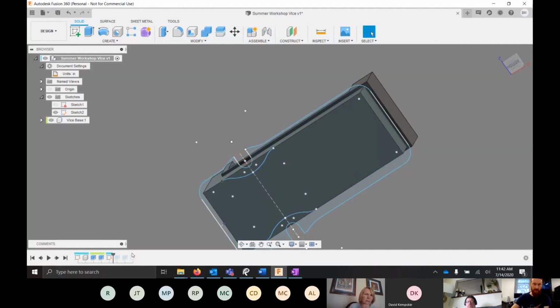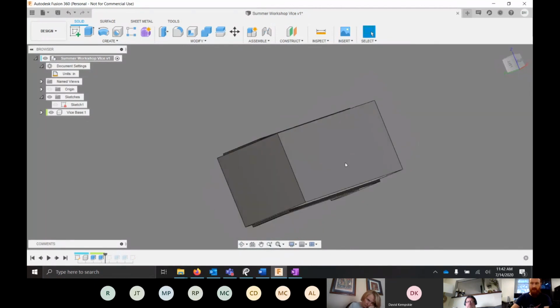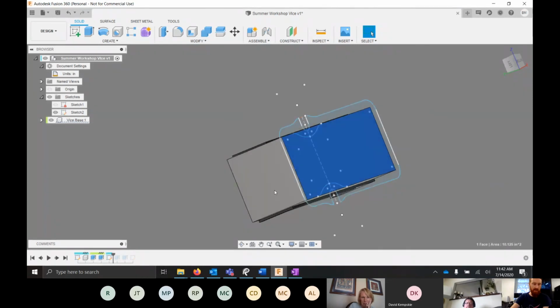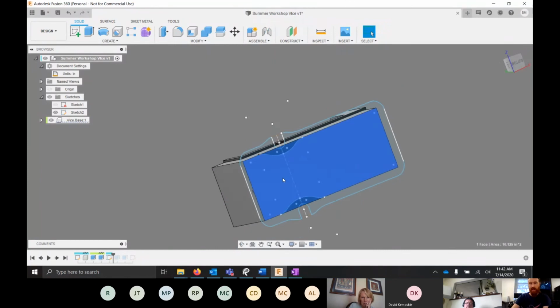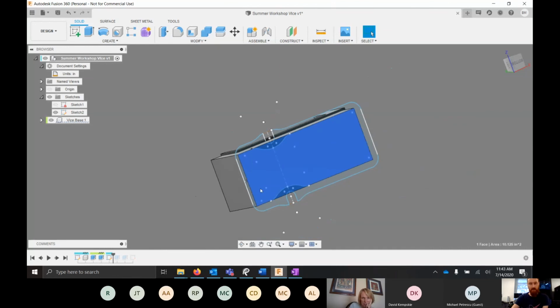If I go here, and I selected this face, it's going to take this entire perimeter and keep it in the sketch, so that if I wanted to pull from it, I could. And so when I did some of my sketch entities here, that's exactly what I did, where I pulled the dimension from this line to this line, as an example.